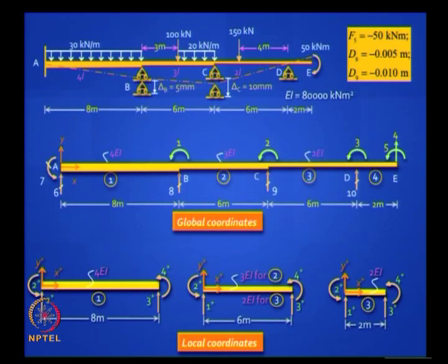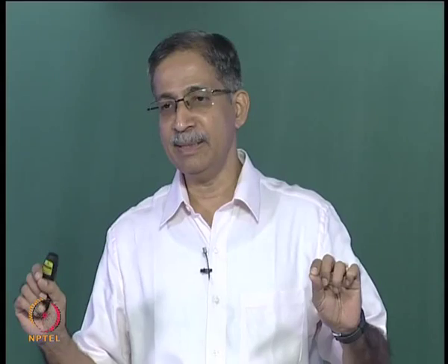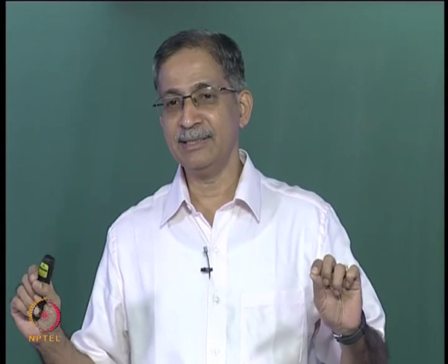And that overhang is also treated like any other element, that is a 4th element, and you have 4 degrees of freedom. Actually you can draw just one element, and the only thing that changes is the length and the EI. It is 1, 2, 3, 4, right. Okay. Now what do we do next? It is good to write down the solution procedure so that you have a road map.